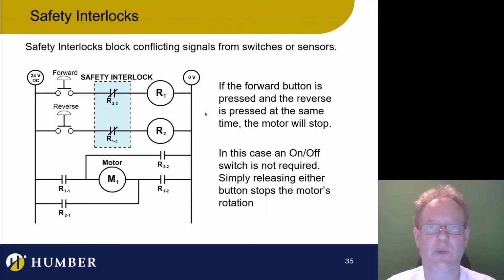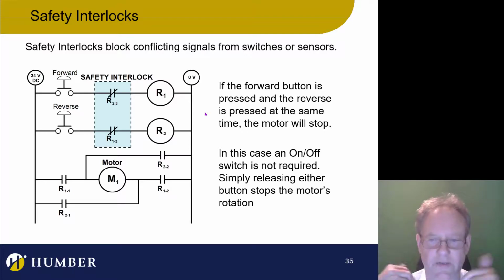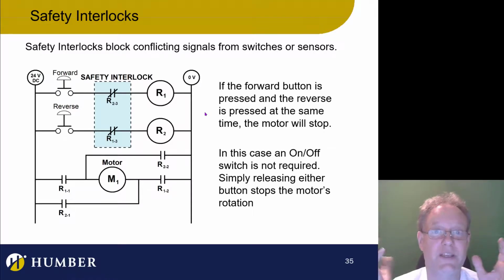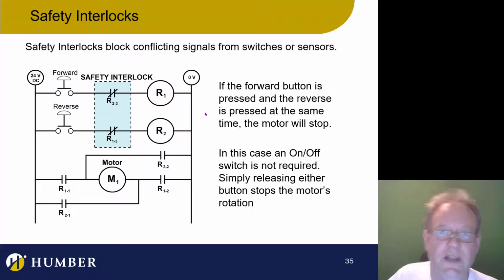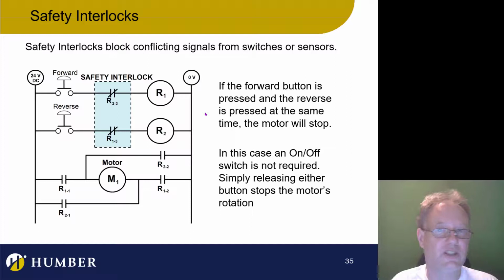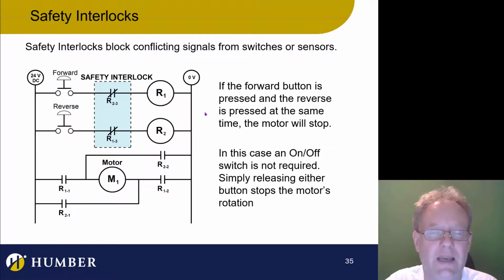Safety interlocks are really important. Safety is actually really important, but safety interlocks are things that we put in a lot of control systems. You have to think about safety interlocks with a lot of things. Like for instance, in a milling machine, in a CNC machine where it's going automatically, dude, the machine will not start unless the door is closed. You've seen that kind of thing before. Some cars, if you're driving a standard, you can't start the car unless your foot's on the clutch. Or you can't put it in gear unless your foot's on the brake. So you know those are safety interlocks.